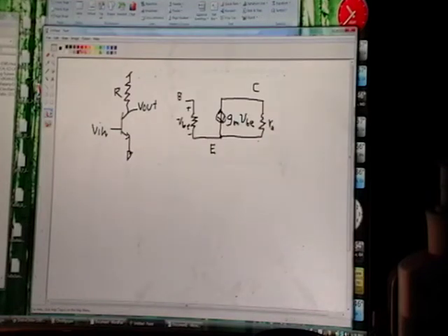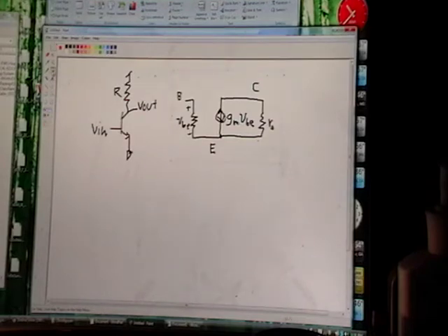let's go back over here. When you're analyzing this circuit as a small signal model, anything but VN, so VN stays in your picture, anything else that's a voltage supply is considered ground. And this is called an AC ground. In other words, kind of a high frequency ground. Or the other name that you hear it called is a virtual ground.